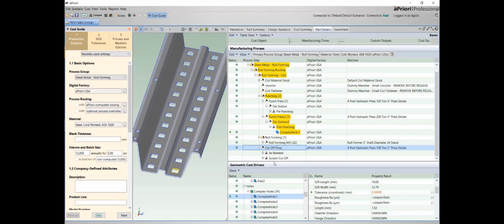But blade dies are assigned when the part and cross-section geometry requires it, such as parts with hem bends or parts where the cross-sectional bends are obscured and can't be adequately supported to prevent crushing by a scissor style die.